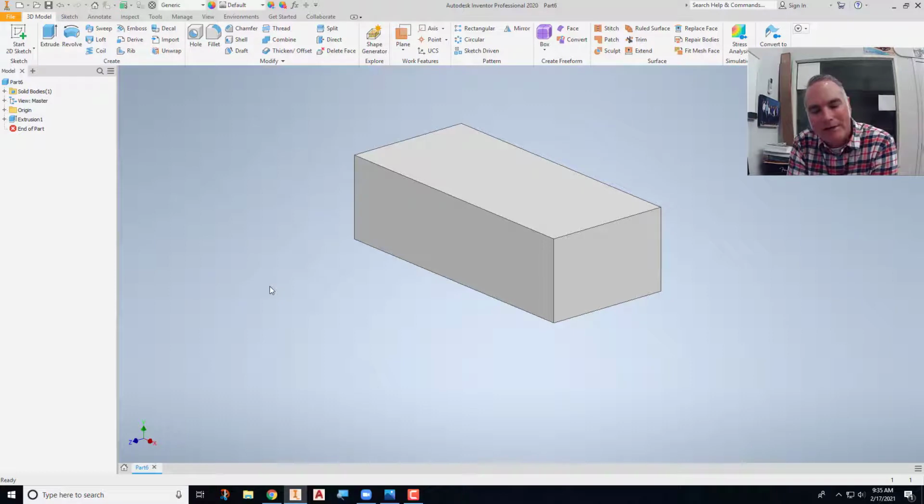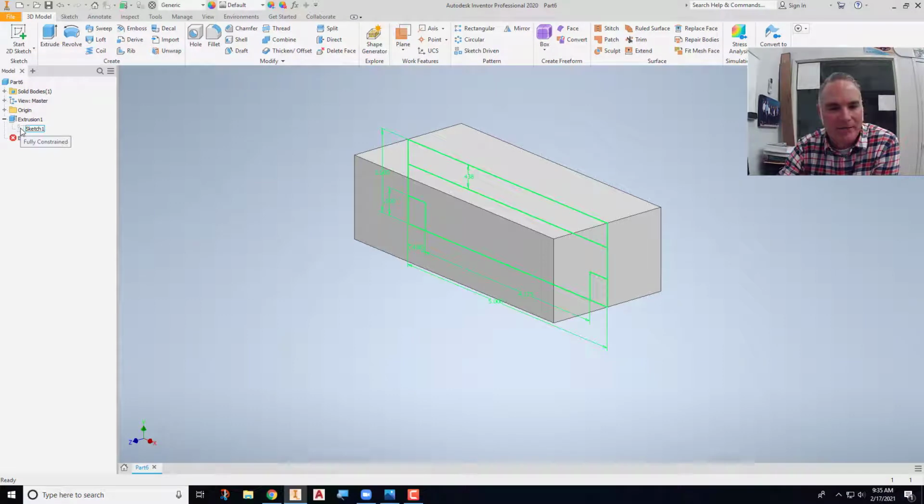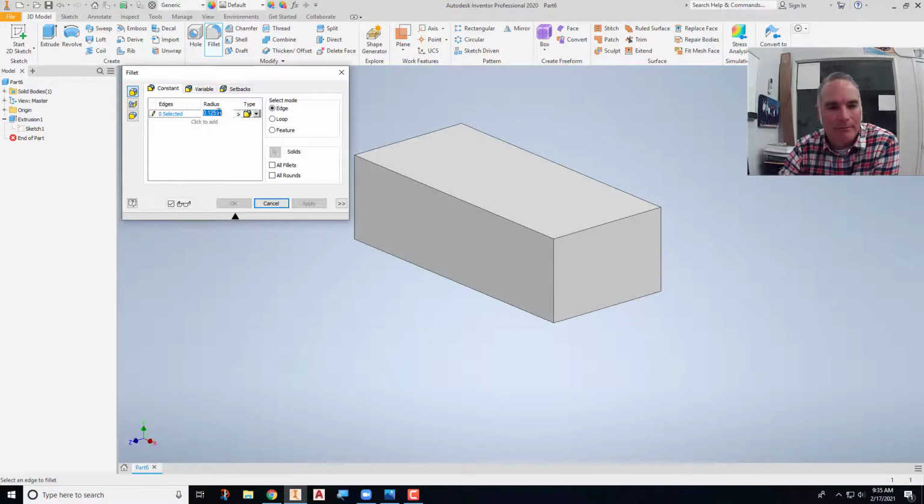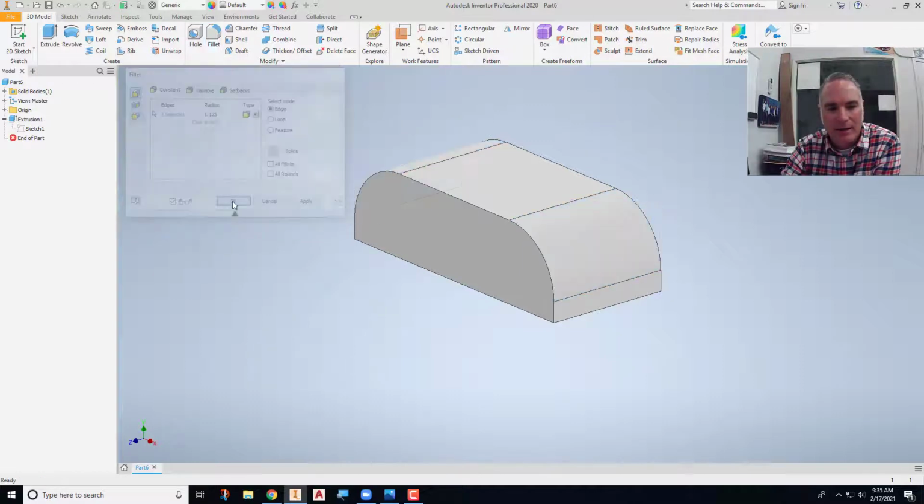And you might think, well, why did you not just have the block? And again, the reason that I don't just want the block is because I've got the rest of that information that's nested in there that I'm going to use after I round the corners off. So my next step here is to go ahead and put that fillet in, 1 1/8 radius, so it's going to be filleted there and there, and I say okay.